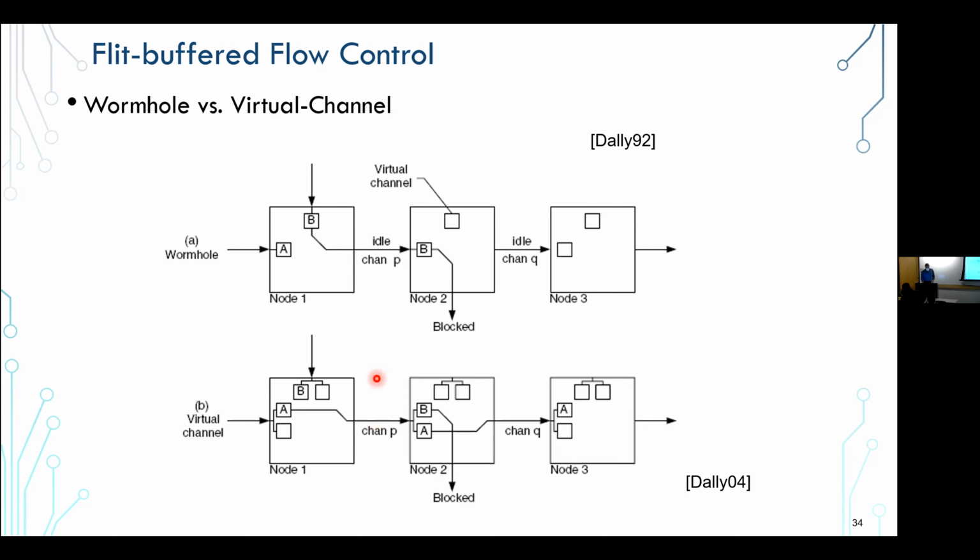Now, this does complicate the architecture of the router itself a little bit. There's no free lunch here, because the router now has to decide for each port among the virtual channels who goes where. So the arbitration in the router gets a bit more complex, but we can take that hit with more efficient logic scaling, different routing algorithms and things like that.